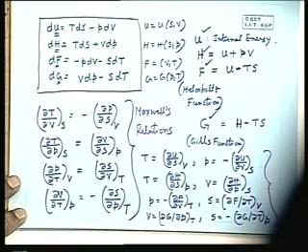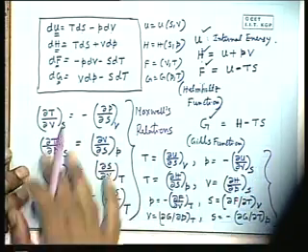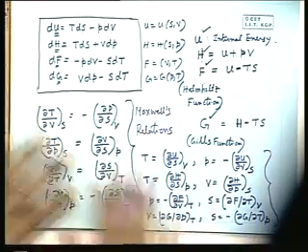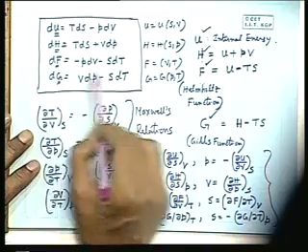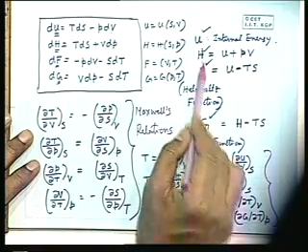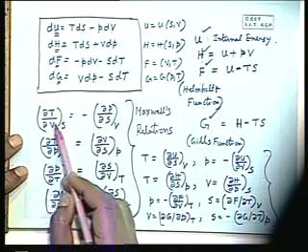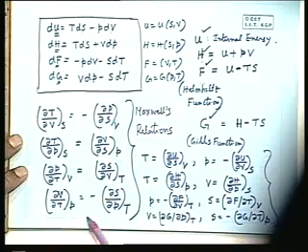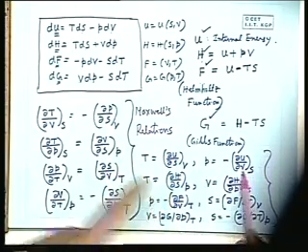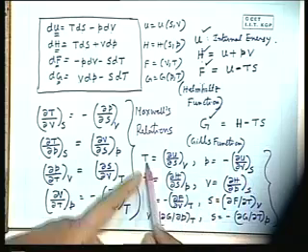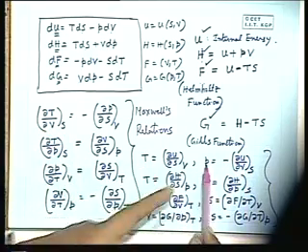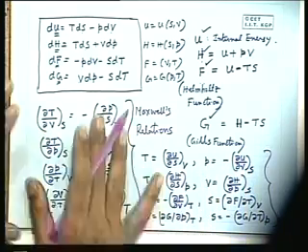In deriving certain important thermodynamic relations, some of these expressions will be required. We can write all those equations from these 4 basic functions. If we express these 4 equations in this form, we derive these equations, and these 4 sets of equations are known as Maxwell's relations. This is the basic definition from which we wrote this, because this is del U del S at constant V, this is del U del V at constant S. So del T del V at constant S is del P del S at constant V. So, this is okay.